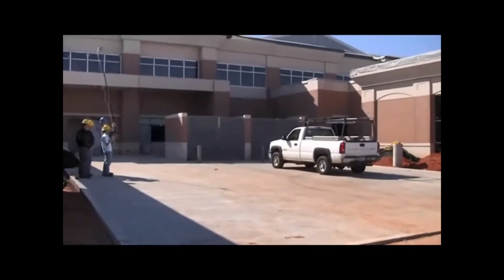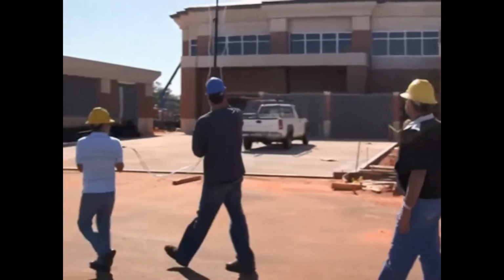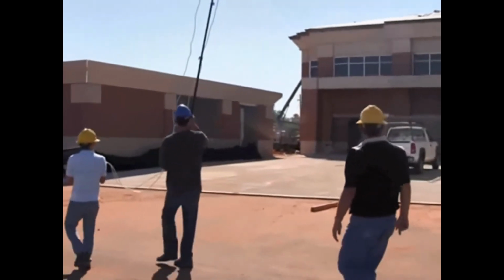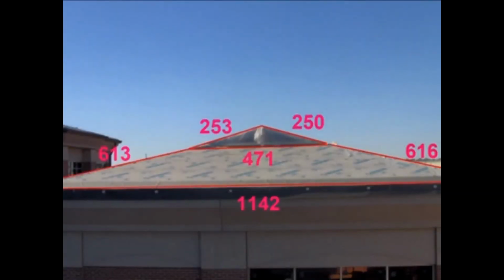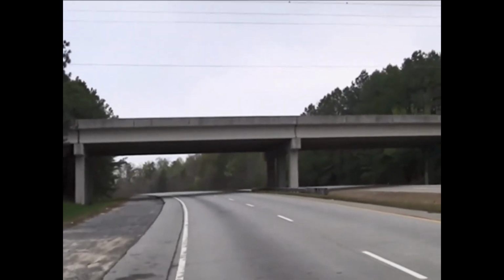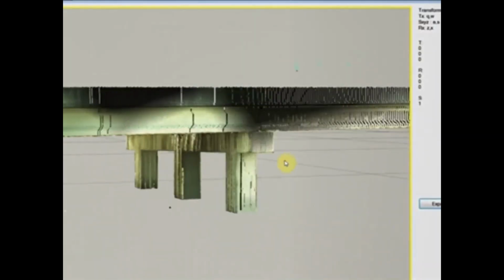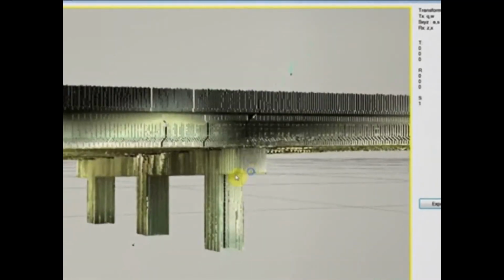Find all the pipe points everywhere, without caring which pipe point belongs to pipe 1 versus pipe 2, right? And then as a second step, we do instance segmentation, which is, now that I have all the pipe points, let's try to understand which one is pipe 1, which one's pipe 2, and so on, and gradually make them an individual component in space, right? That is so far the general strategy we followed. Same thing for flanges, same thing for angles, same thing for all the other elements we've used in that space.